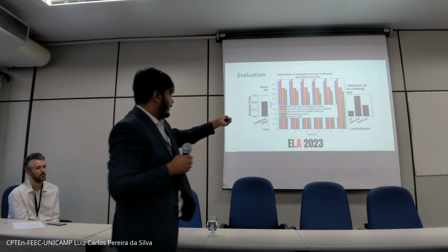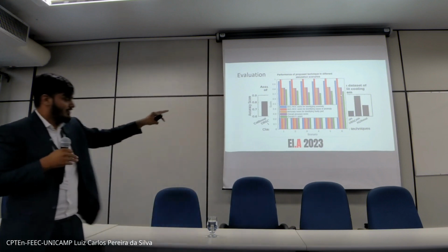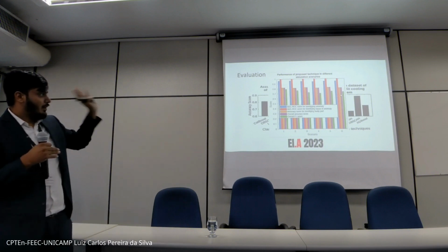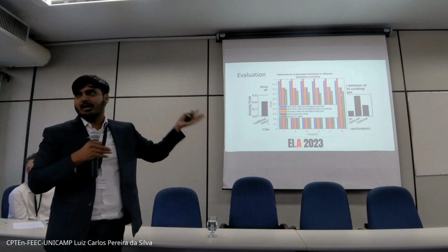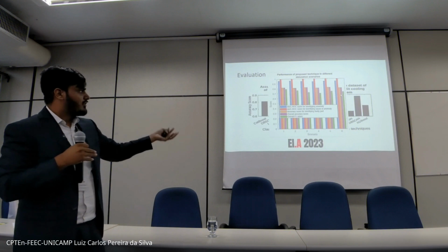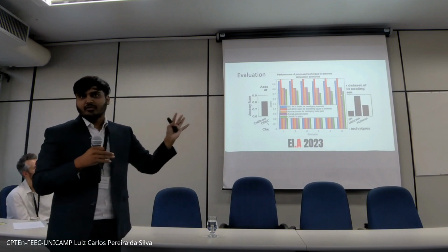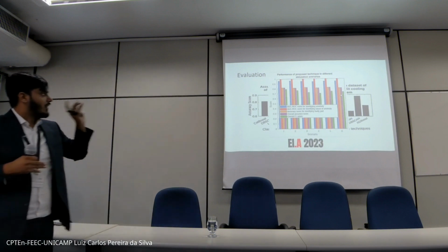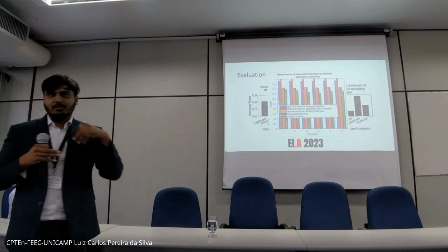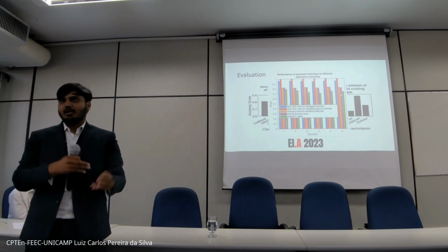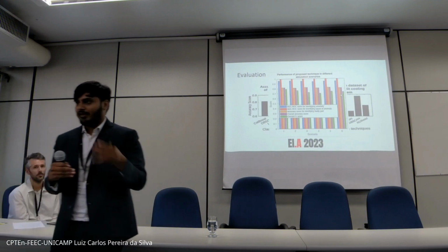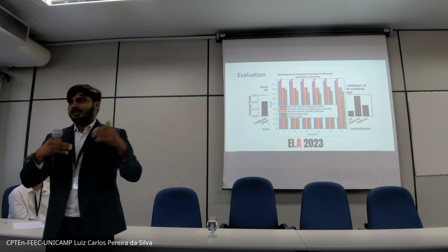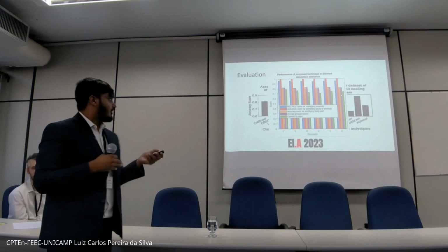Here we also show in six different simulation datasets how our solution works. For each stage, we show the AUC ROC score, the accuracy score, and the overall F1 score for the entire system, which is around 0.76. For stage two, because we are using a rule-based approach, we always got an AUC score of 1, because those are based on rules, and we designed the rules very carefully using the ASHRAE guidelines.